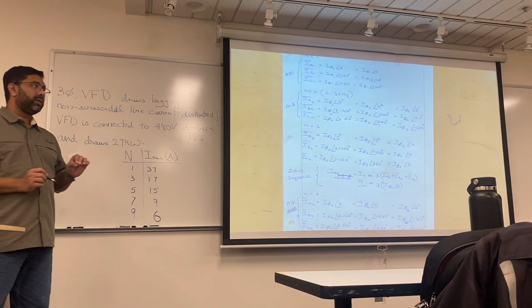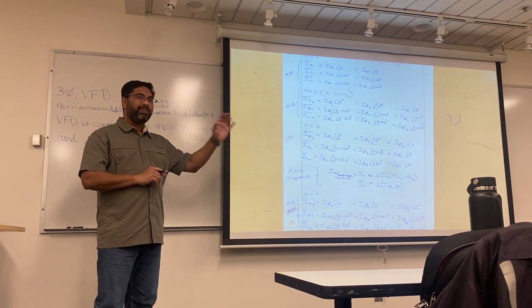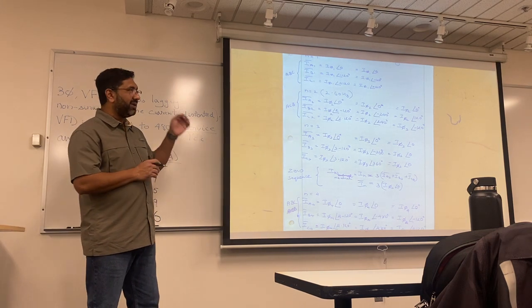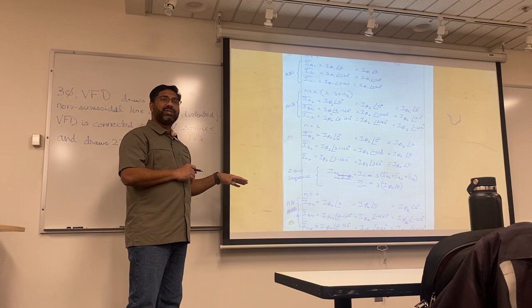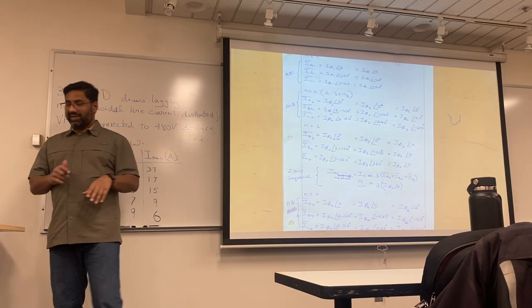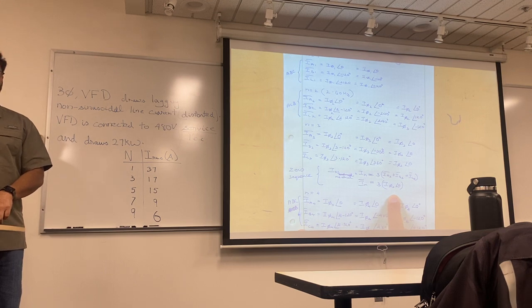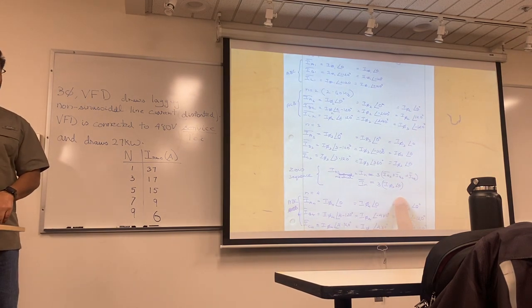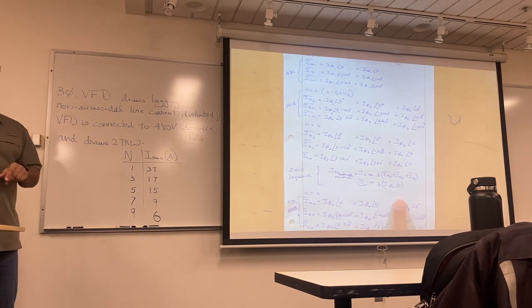And think about this. You designed a breaker 1.25 times, great deal. You put a conductor. You are assuming that your neutral is going to work, not really. The neutral is actually having 3 times the phase current. So be very careful, figure out what your loads are. It's not enough that you have a source. You also need to figure out how your loads are responding.